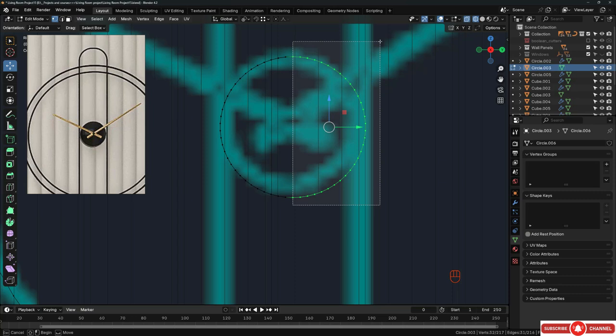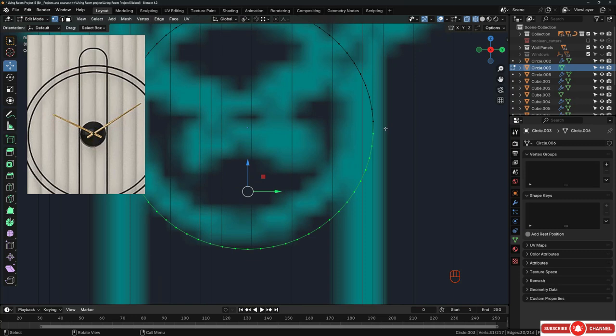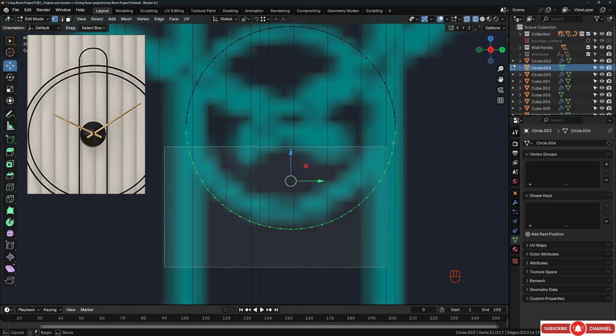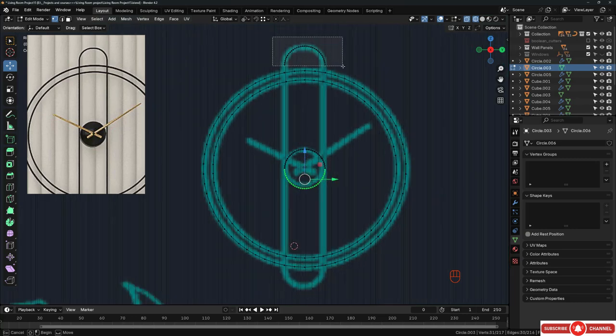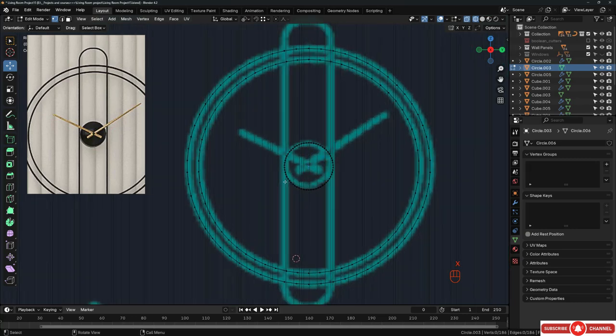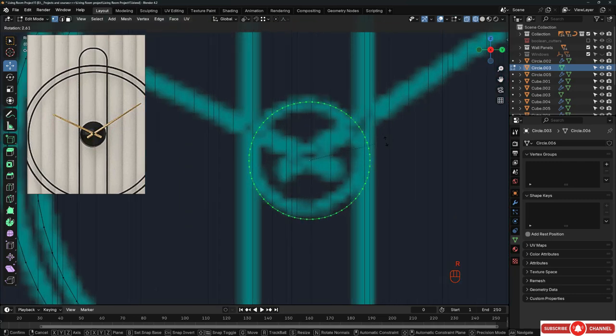All right, yeah. The problem is if you create a selection like that, and if you put the selection perfectly in the middle, I don't have vertices at the middle, as you can see, and that will affect the curvature of the shape that we are trying to create. So in this case, what I'm going to do is I will delete those, hit X V, and I will grab this and rotate it 90 degrees. Just rotate like that, 90 degrees, and you will fix the problem.